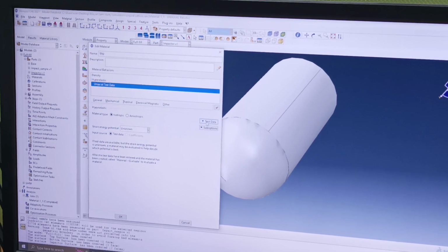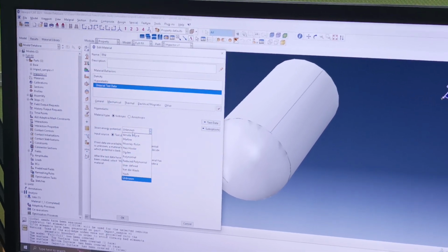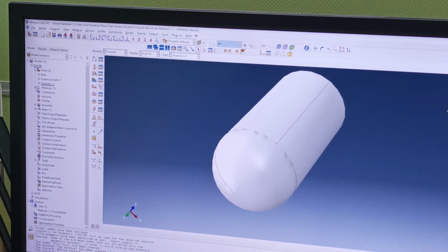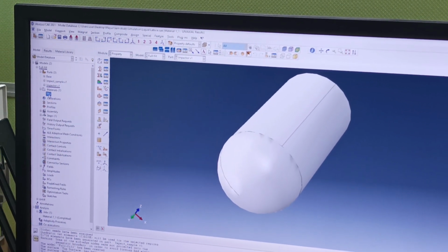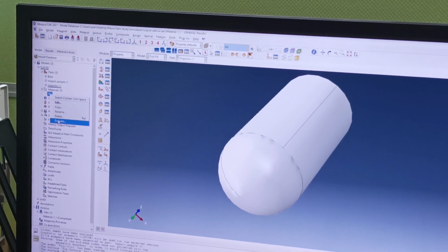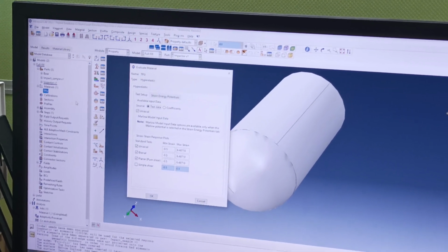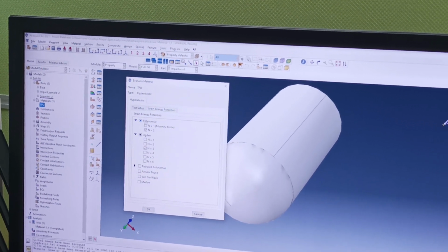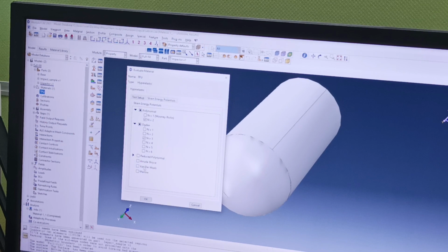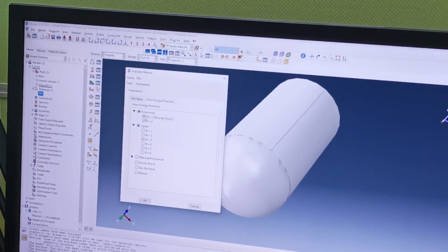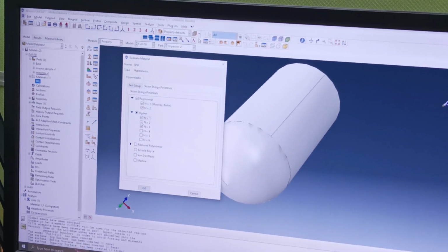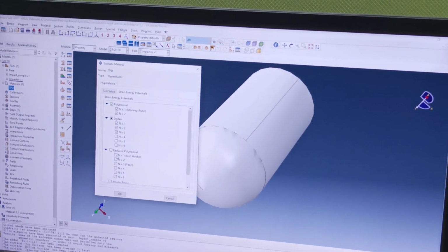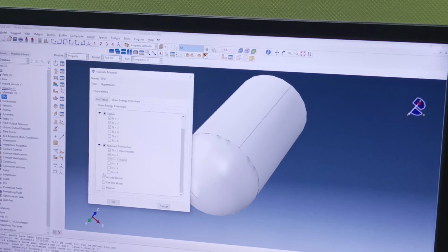I've just uploaded the test data, but I don't know which one is what. I just press OK, and then I click here, and this TPU, I will just click on evaluate. Because I've already set the hyperelastic parameter, it will give me the different strain energy potentials like this. So usually I will just take polynomial. I will take Ogden 1, 2, 3. Maybe if I want, I take a reduced polynomial 1, 2, and 3 up to this.